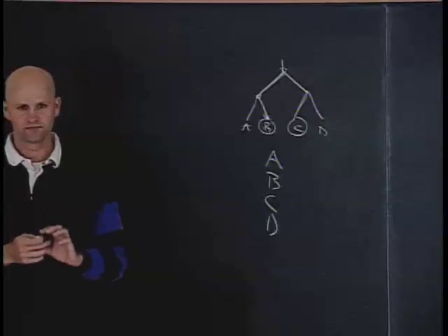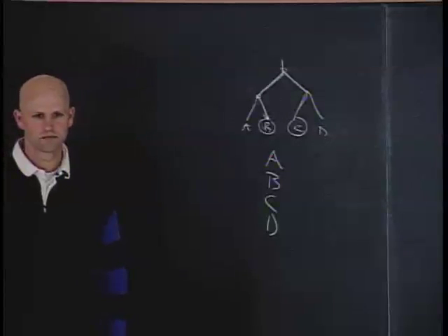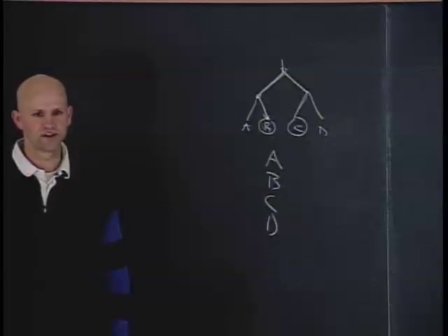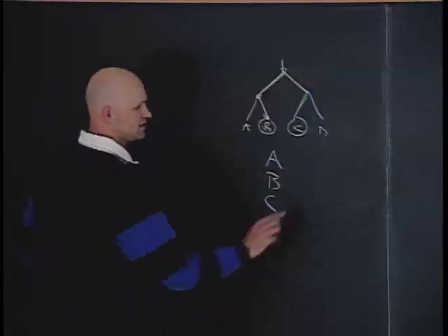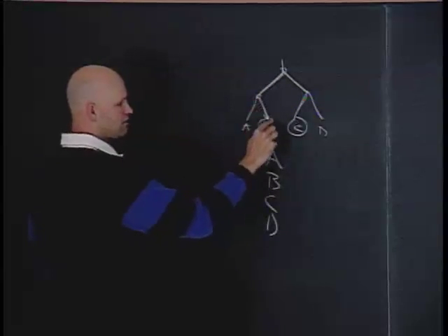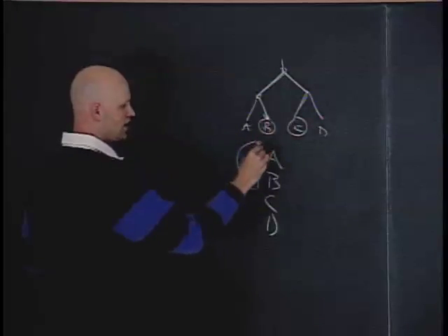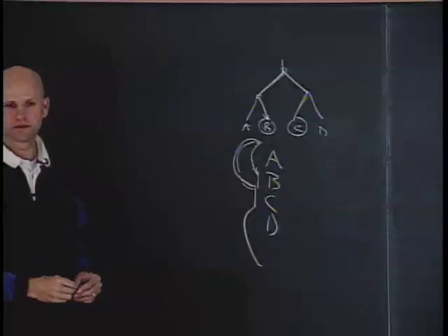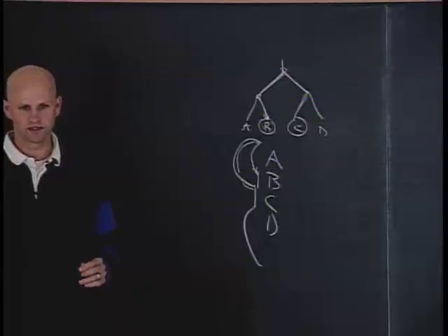Good question. Well, I guess my question would then be, how could the hardware know? Like, how does it know beforehand if half of all the threads are going to run B, or if it doesn't know at all? It compiles the code to look like this, pretty much. But it's smart in taking that controller, and it'll take this jump here and then come here, and then when we branch to B, it'll just skip over that and then run this. Then it'll go back here and decide, oh, I need to run C. I'm going to come here, run here, and then skip out. Okay? So in that sense, it acts like a microprocessor would. It's actually jumping to the right piece of code.